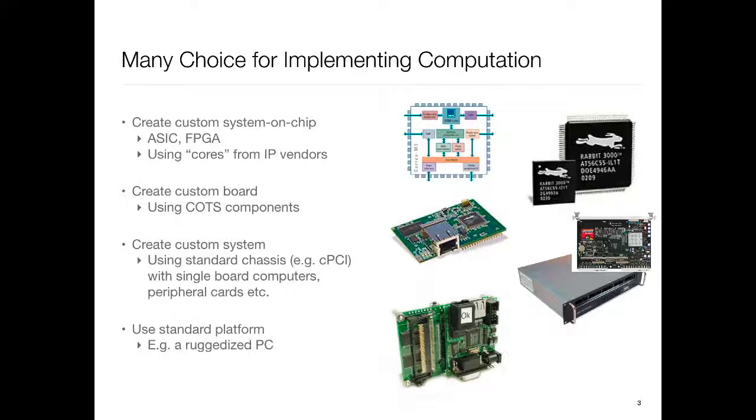So that's one. Second one is that you pay more money and you get access to the HDL level, the source code. And then the final one, which very few companies are able to afford, is that you become an architecture licensee. That is, you get the rights to modify things and design your own processor with the same instruction set. So for example, when you look at ARM, there are only 3 companies which, as far as I know, have the architecture license, so they can design their own processors compliant with ARM: Apple, Samsung, and Qualcomm. And even the latter two have moved away from it, so they basically use processors that ARM designs, and then they just put them on the chip.